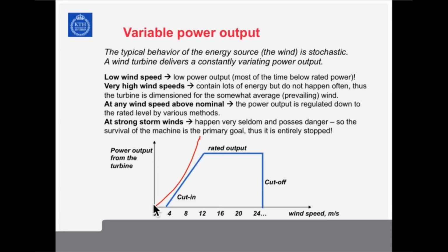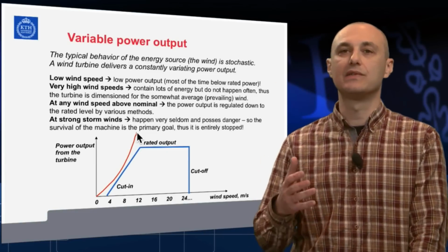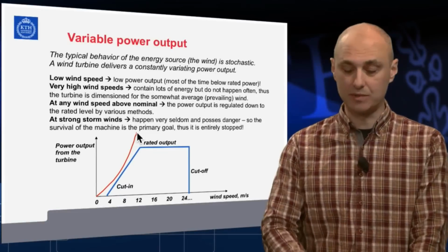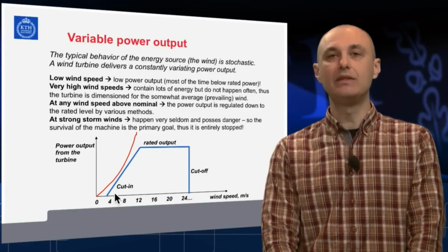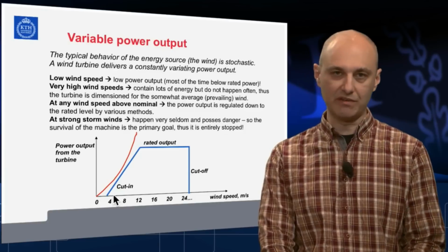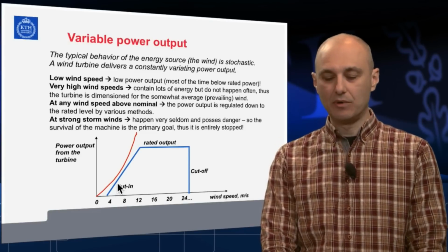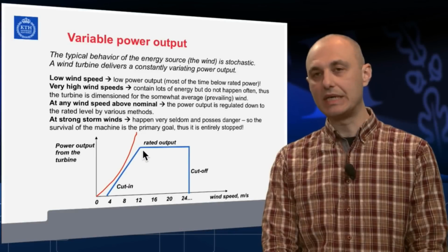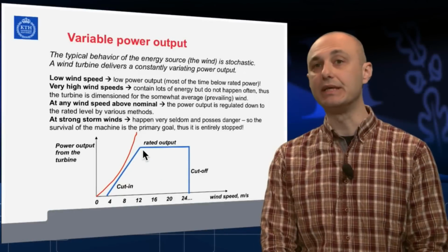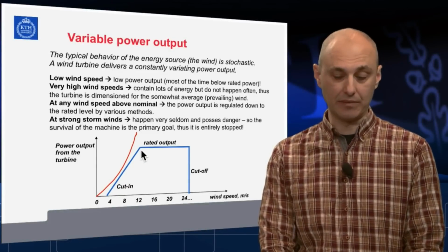This is a rough attempt here to represent the actual available energy in the wind, but you get the bottom line. It is a function of the cube of the wind speed. So the wind turbine is never able to convert all the available energy. It converts part of it, and the more we go towards growing wind speeds, the less efficient the machine will be.